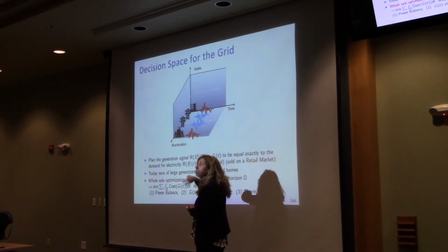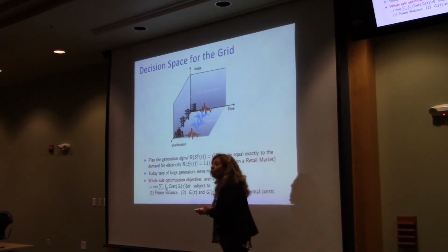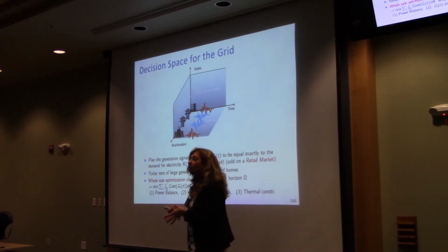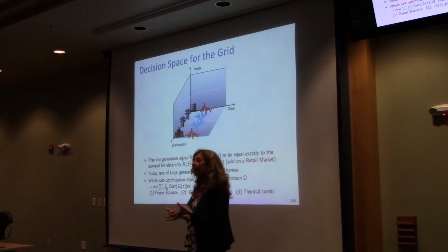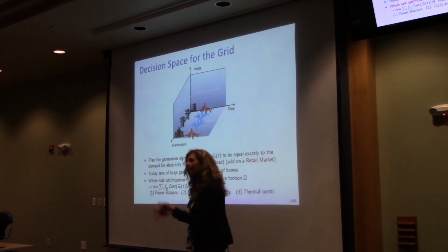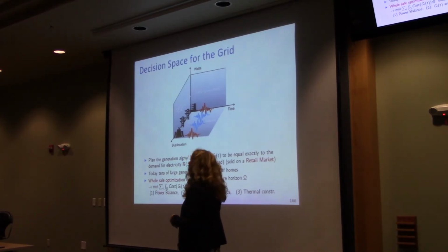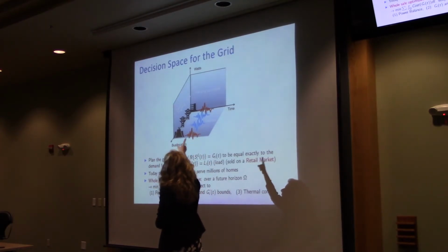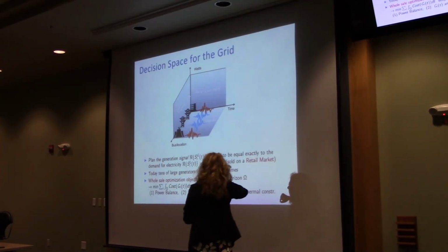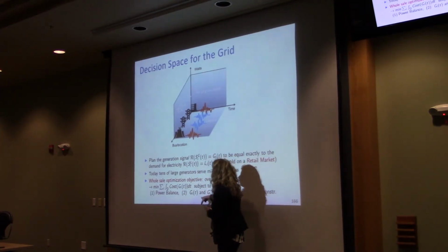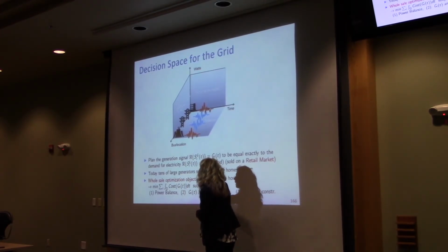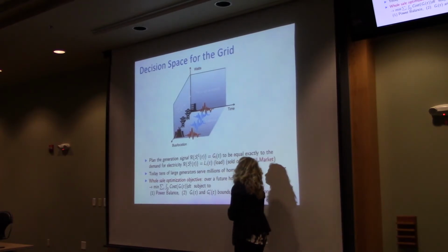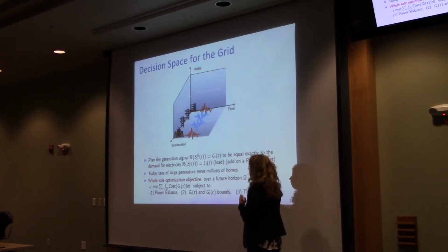And do you have any constraint in time? Actually, you do. Those equations, the swing equation, do provide a constraint. You have what is called a ramping constraint. These big generators cannot inject mechanical power to compensate and ramp the power up and down instantly. So this provides constraints that operate in the time dimension. When you look at a certain horizon, you not only have to consider the power balance constraints and the transmission line constraints, but also the capacity constraint and the ramping constraint of your network.